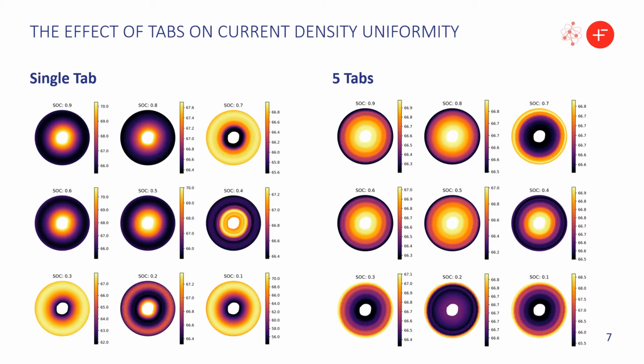And this heterogeneity arises because there's actually a reasonable amount of resistance in the current collectors. The length of the jelly roll is quite long. For an 18650, it would range from about 60 centimeters to a meter, and for larger cell formats such as 21700, you're looking at more like 1.5 to 2 meters, depending on the thickness of the layers. And because they're only 20 or 30 microns thick, you actually get a reasonable resistance in them. And so imbalances in the current can also lead to imbalances in the thermal behavior as well. And this will have a knock-on effect on cell performance and degradation mechanisms.